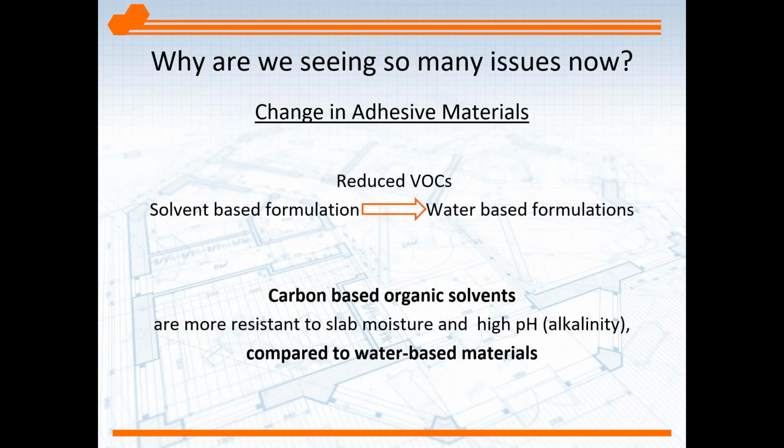Many years ago, we moved from solvent-based materials to water-based, and with the adhesives that were available, water-based products are more sensitive to moisture. They can re-emulsify, or a high alkaline environment can also defeat or cause damage to adhesive. Nowadays, many of the adhesive manufacturers have made great strides in reformulations where their water-based products can hold up to moisture vapor. But this was the start of a problem many years ago, that water-based were just not as good as solvent-based, petroleum-based materials.